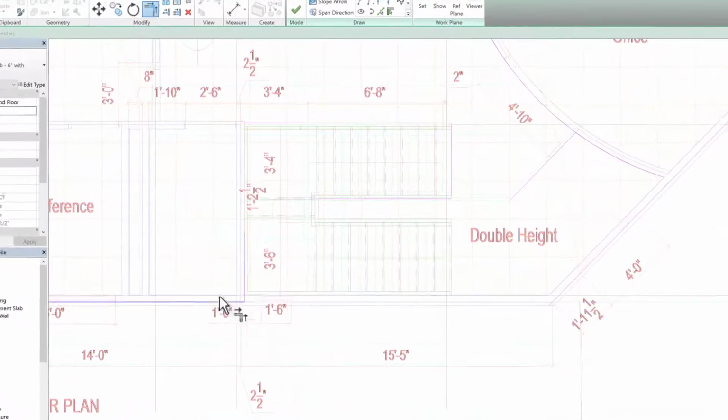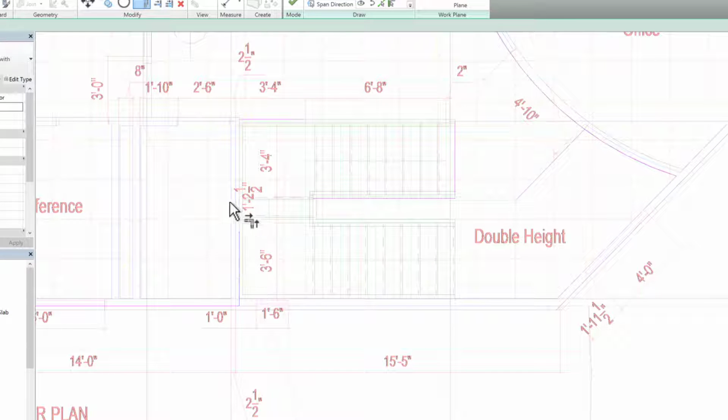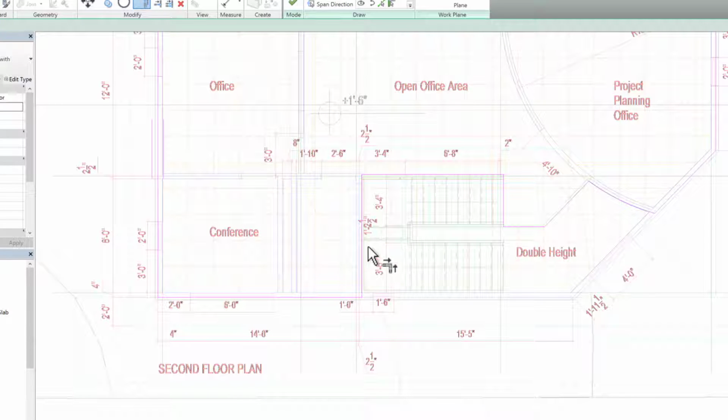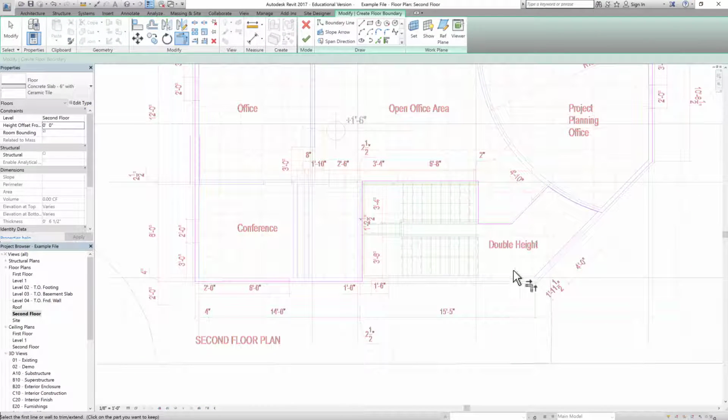Now let's extend to this corner, so our floor will come this way and then extend to this. So it will go this and turn from here, come this way, then I want it to join this way, this way, this way, and this way. So as you can see here, the floor will go inside like this in this profile and come out like this, so that this remains a cut in the floor, so that our staircase can go up and there is a double height or see-through or see below from the top.